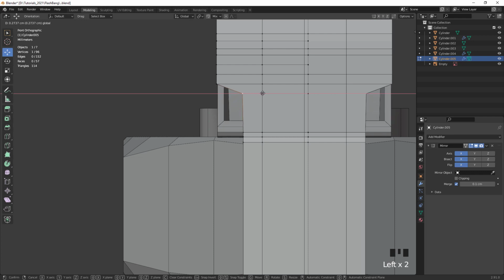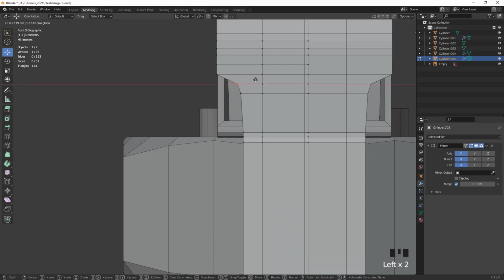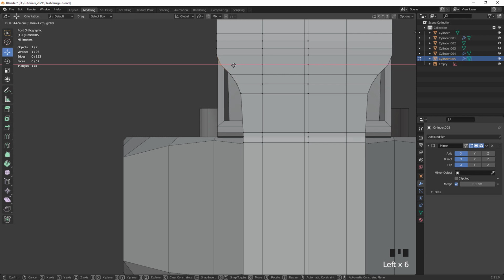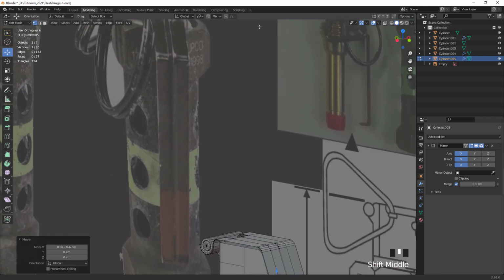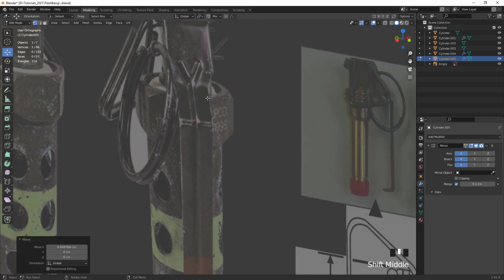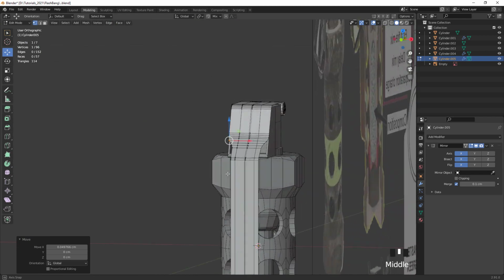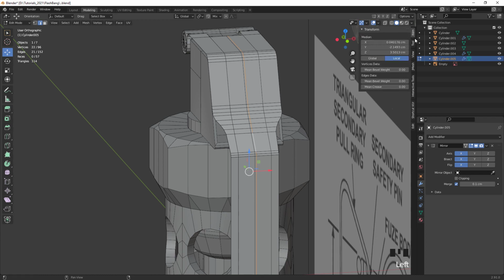Now that vertex point we can also adjust manually, and we're just gonna basically shape this nice curve here with the vertex points that we already have there. So now we have this element here. So let me just select these edges again here at the center. Press Alt to select all of them, and then under Item, I'm gonna center it at 0.